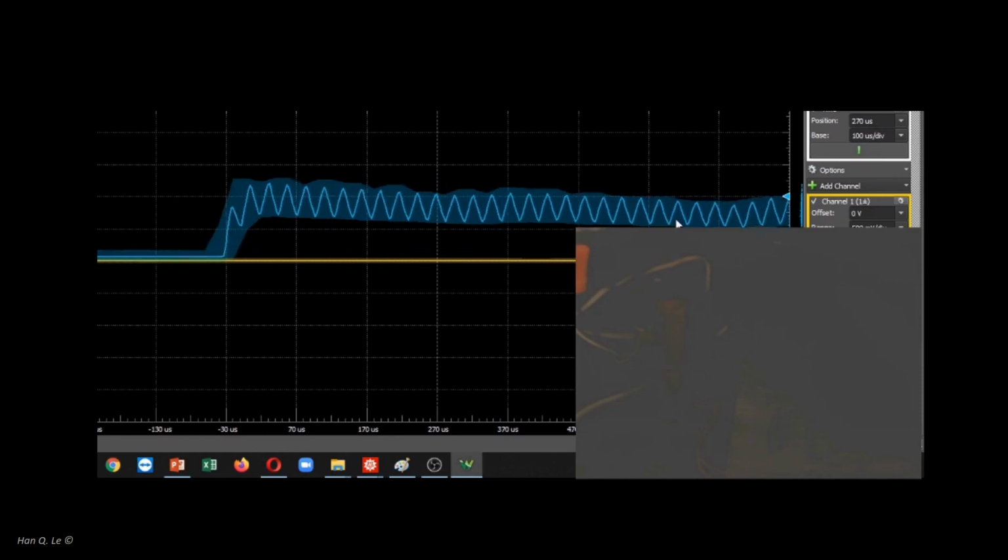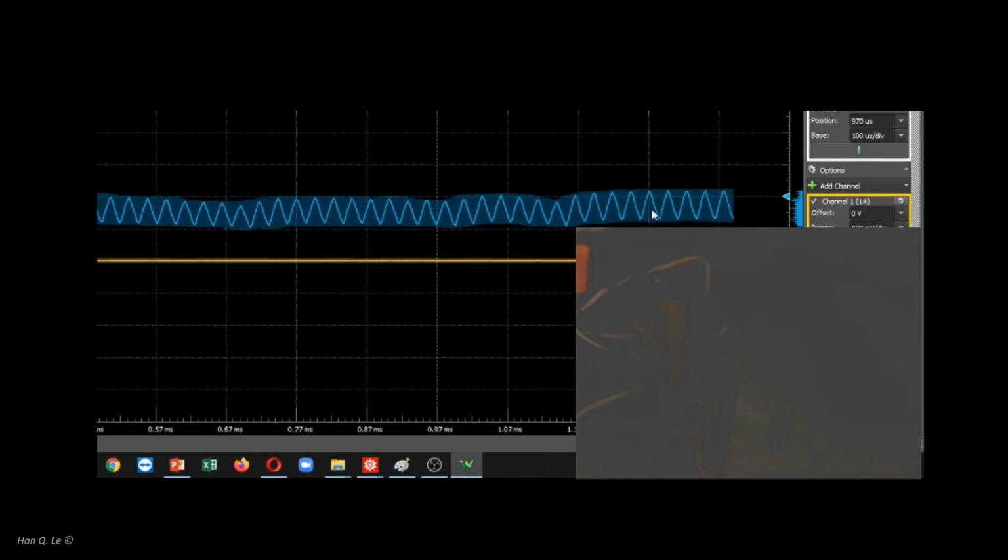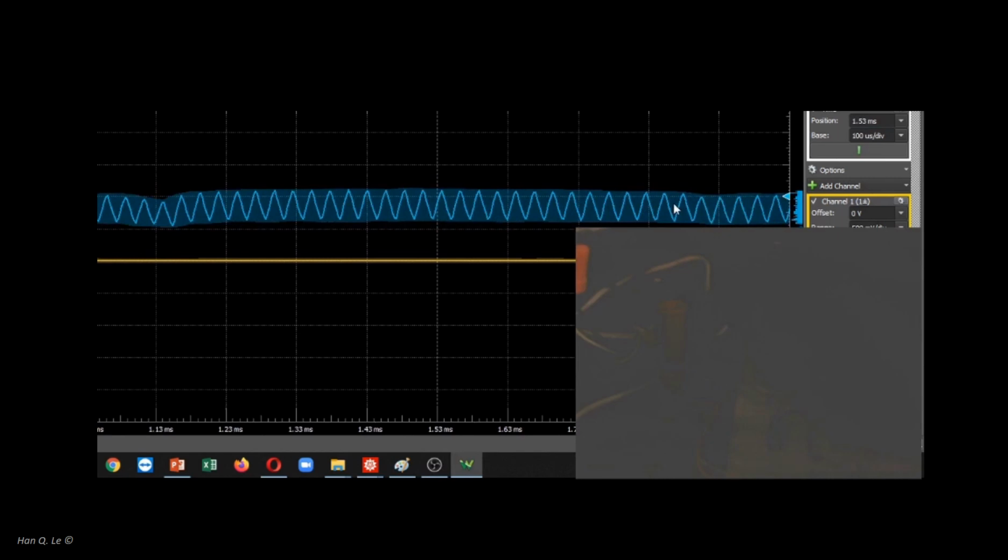The modulation should be square wave-like, but appeared to roll off here because the optical receiver gain was high and the bandwidth was low, hence the gain was set lower.